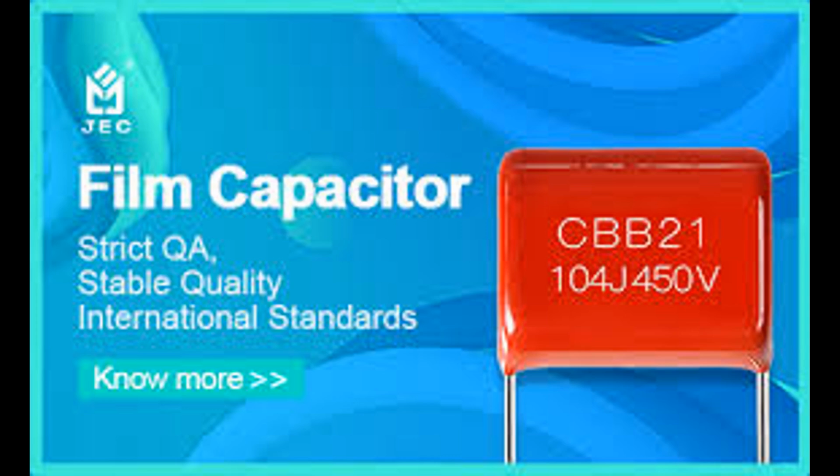Summary of how film capacitors work. Charge storage. Electric charge accumulates on the electrodes, generating an electric field across the dielectric, plastic film. Capacitance. The amount of stored energy depends on the surface area of the electrodes, the distance between them, and the dielectric constant of the film.